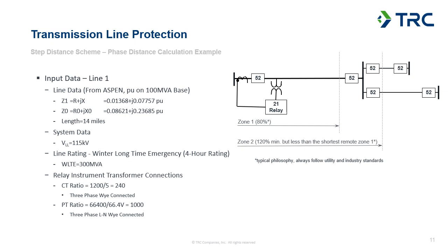All right, so next we're going to take a look at a step distance scheme calculation example. And once we go through this fairly simple, straightforward application, we'll talk a little bit more about some of the other kind of unique aspects that you might run into for some more complicated transmission protection applications. So we'll start out taking a look at our phase distance calculations.